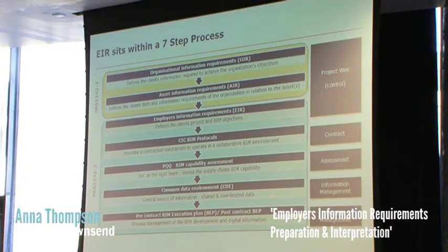And within the EIR, we identify that it should make reference to the CIC BIM protocols, which we'll touch on. That provides a contractual mechanism to be able to operate in a BIM environment. It addresses designers sharing their models, developing their models to the relevant standards defined in the EIR. It addresses copyright and intellectual property issues. So that's a document that should be appended to all design team appointments in a BIM environment.